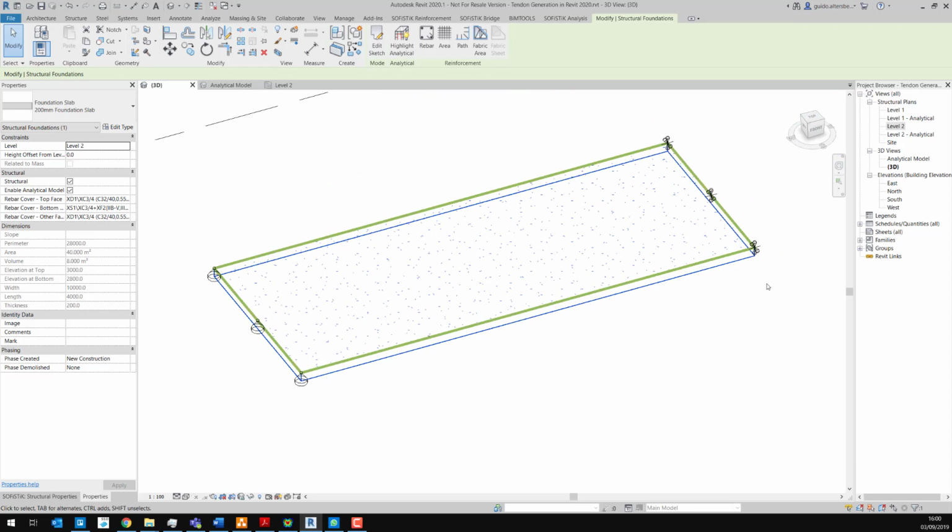Okay, what do we need to do first? The first step in the generation of the tendon geometry within Revit is to create model lines. These Revit model lines actually represent the projection of the tendon and will be used later on also to assign further information of the high points. So generating a model line is a straightforward thing.